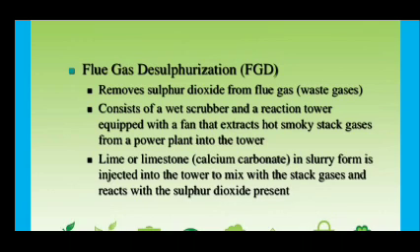Lime or limestone in slurry form is injected into the towers to mix with the stack gases and react with the sulfur dioxide present.